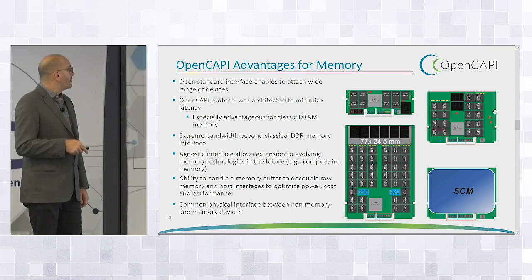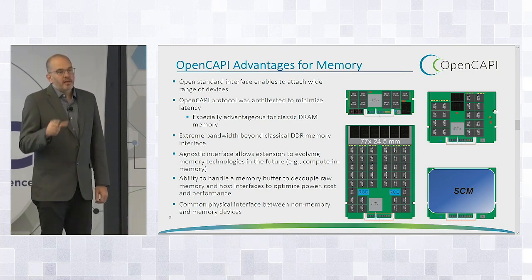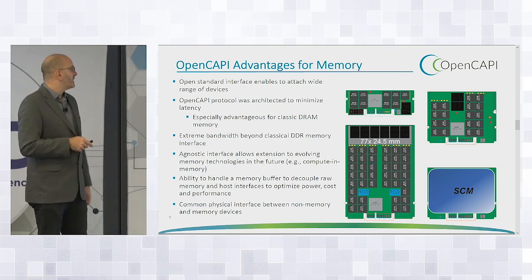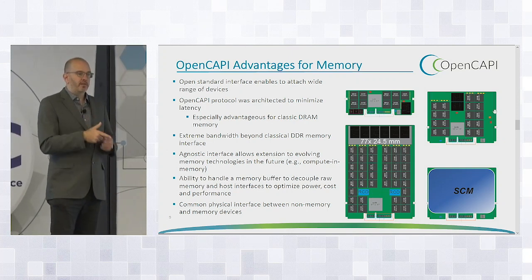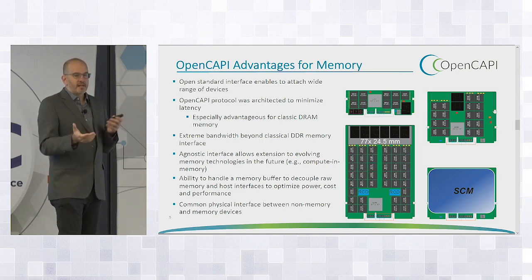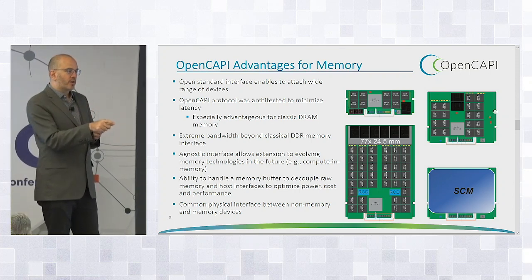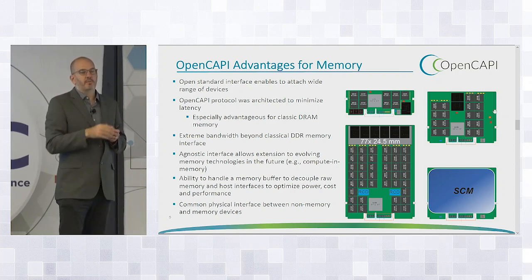But one thing we've done, and this is something that you'll see that's a little different from the next presentation, is we've optimized this for extreme low latency. And by extreme low latency, we have about a 5 nanosecond delta between using direct attached memory or this SerDes-based memory. That's accomplished with a lot of tricks in the protocol that we've developed on previous buffered solutions, right? And that's a significant difference from other protocols. Now that said, that means the protocols themselves are very much associated with a direct host attachment, right?